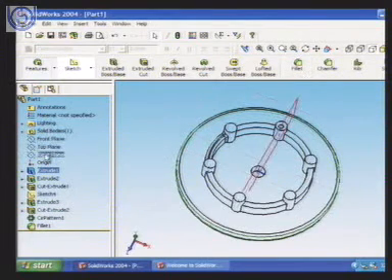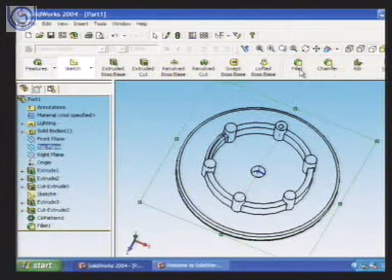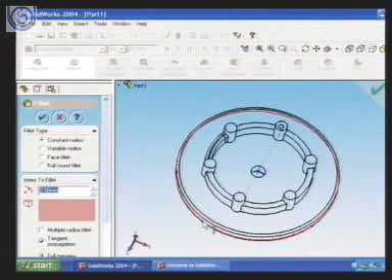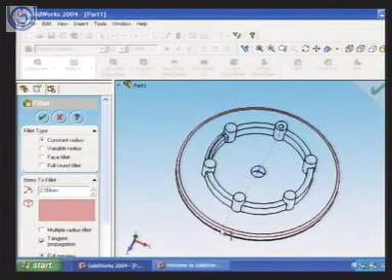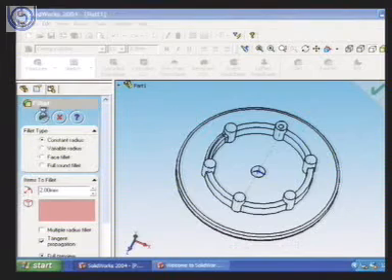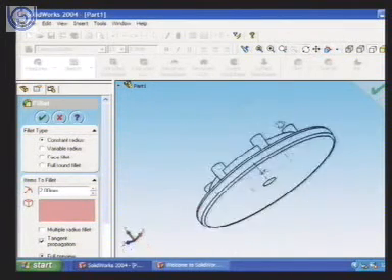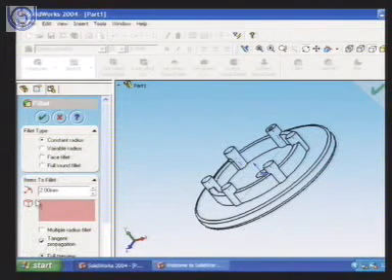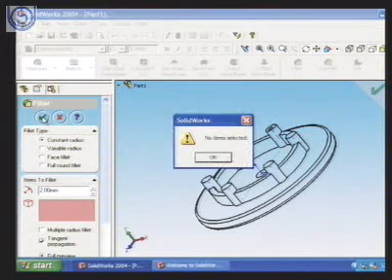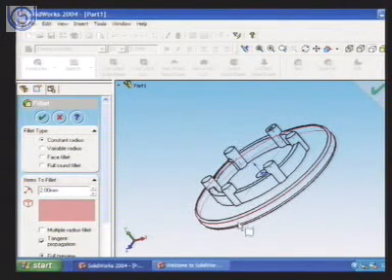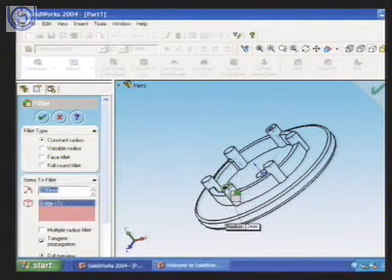It will not do unless we select the plane. Fillet, I say here 2 mm, I select the surface here and I say OK. Items not selected. It has not selected the plane, so it will not do the fillet. Now I say here, now it has still not selected, or it has already done the filleting. Let us do it here, edge, and I say 2 mm.